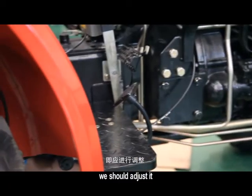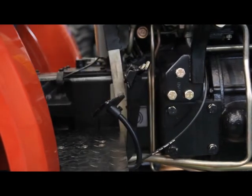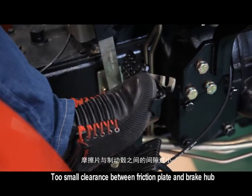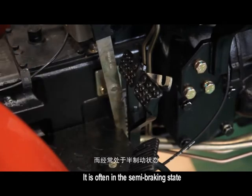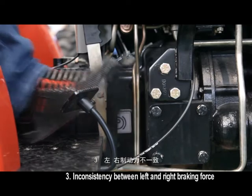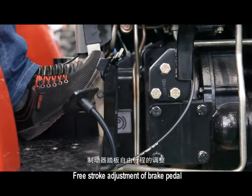We should adjust it: 1. Free stroke of brake pedal is too large and brake failure occurs. 2. Free stroke of brake pedal is too small, or too small clearance between friction plate and brake hub, so it is often in the semi-braking state. 3. Inconsistency between left and right braking force, so the tractor may be off-tracking.